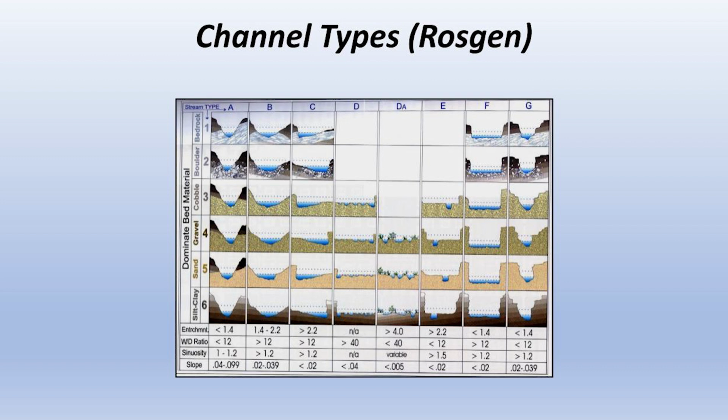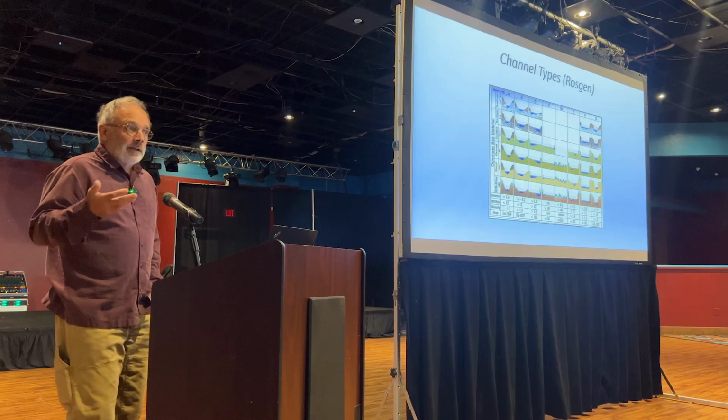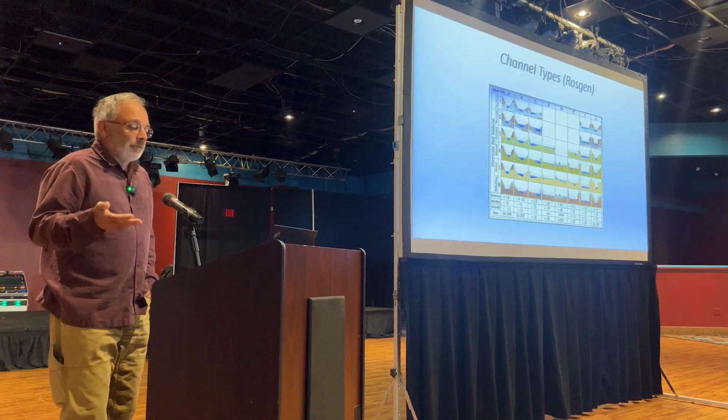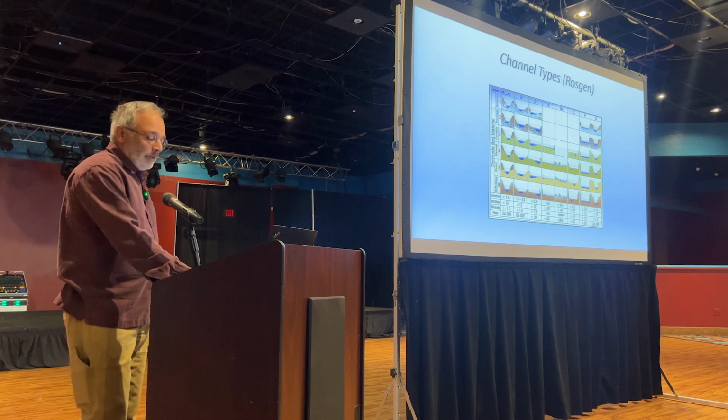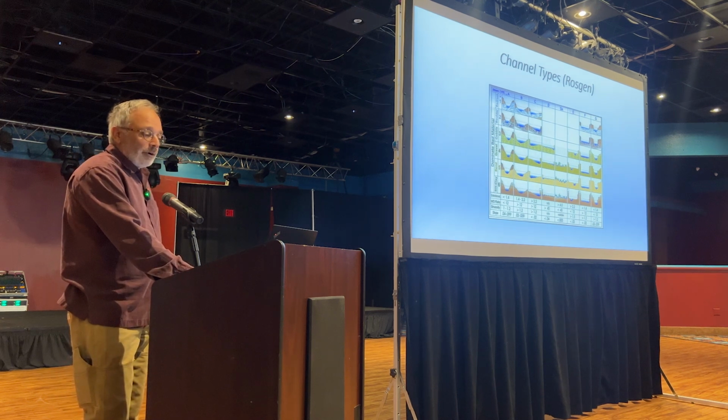They want to sink really quickly because they have no floodplain in order to dissipate that energy at high flows. So those are both high sediment sourcing channels. And when we find those areas, we kind of zone in on those. Okay. D channels are another aspect altogether, and they are unstable, but they can aggrade sediment.